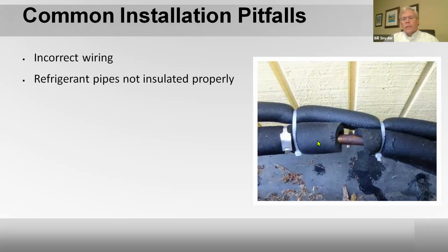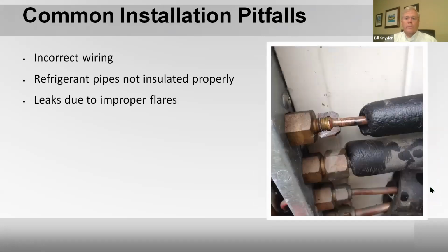Real important to insulate both lines. They should be sealed properly so that there's no dripping or line loss, and that they both be installed insulated, both typically strapped together. That would be the way we do it.